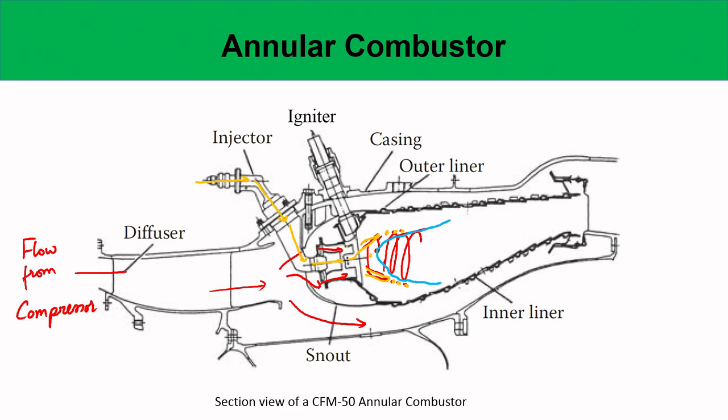But these are the swirlers, which essentially swirl the flow. As the swirl numbers are selected, you will see that the swirl number here is essentially the ratio of the axial flux of the tangential momentum to the axial flux of axial momentum. So it essentially provides a tangential momentum, or a rotational motion, to the otherwise straight flow.